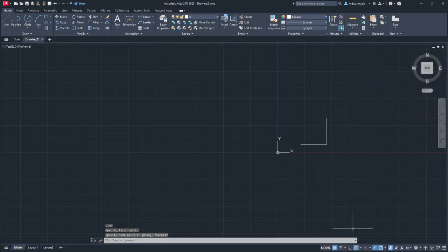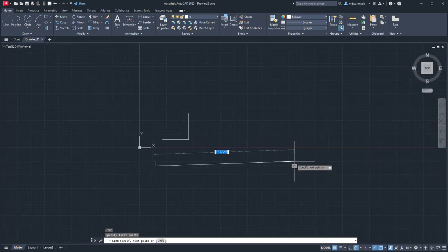So I would say generally when you're working with some of these assistance tools that it's providing, choose the right set of snap tools here, and then overdraw. So like if I'm only going 10 feet out, this is about 10 feet compared to that, right? If I'm only going 10 feet out, I'm going to move the mouse over to here. Let me actually move it so it's centered. I'm going to move the mouse out here.